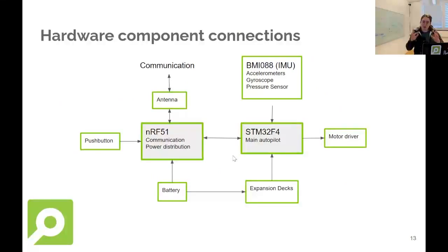And here's kind of like a framework of what each of these components do. Like I said, the STM is mostly for the main autopilot, which has all the controllers, the state estimators, perhaps some autonomy on board as well, but it handles mostly the stable flights. It controls the motors directly, and it also communicates directly with the expansion decks that I'm going to tell a bit about later. The IMU is on there, but of course you also have the NRF chip and the STM chip that constantly communicate with each other, because the NRF chip is the one that is directly communicating with the computer. And also it handles the...